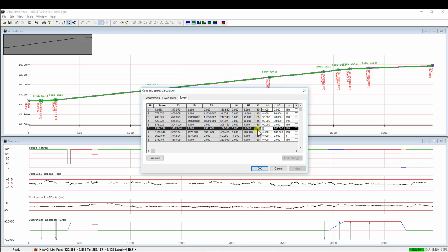And then the same, we have another clothoid. So we have from 0 to 100. We can accept this, and then we continue with a constant radius and a constant cant, and then we descend from 100 to 0 as that is a clothoid.